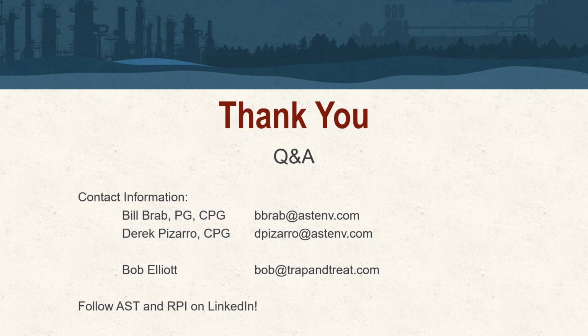It comes from experience. It's reading output pressures in the freshwater test. It's reading the system and output pressures during injection. Sometimes it's even visual. Bill had a slide up from a site, I believe it was in Connecticut. At that site, I think our estimates for ROI at most of the intervals were 50 to 60 feet between boreholes. And we know at that site that we got almost 130 feet because it started to weep out of that contact zone along a road cut there. So we actually had someone monitor that because we didn't want to continue to propagate product out of that zone.